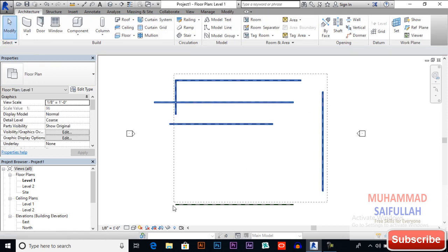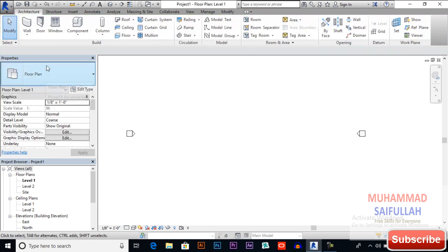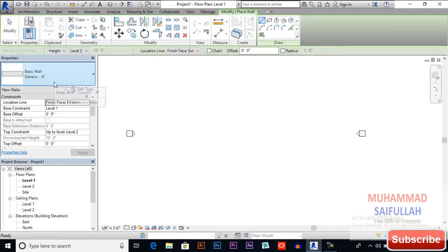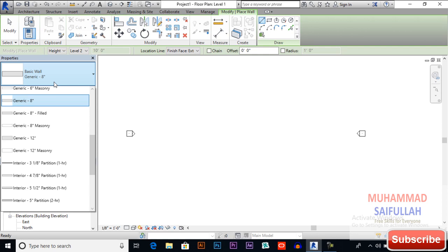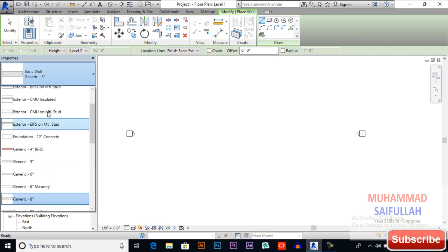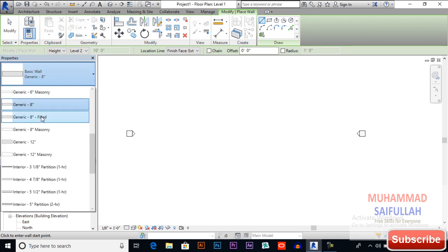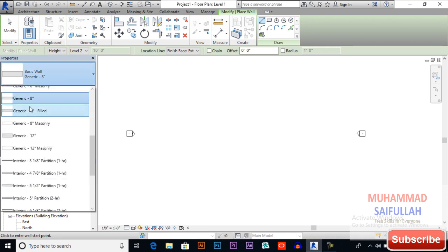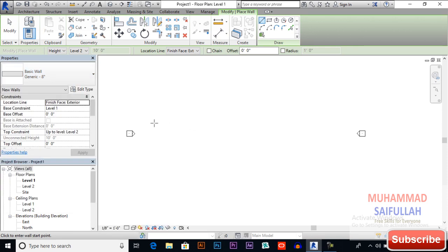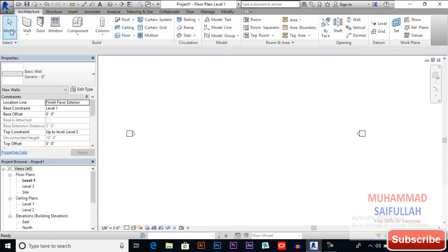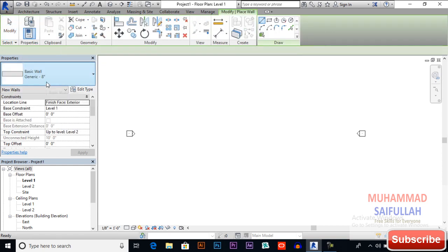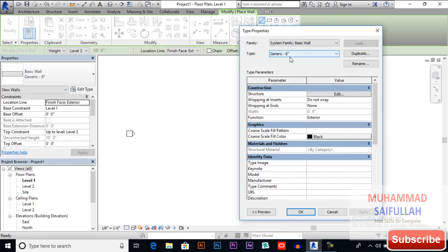Now I will discuss some more things. You can select or change wall types. We already discussed it. Now I want to make changes in some of my wall types. For example, there is no 9 inches wall here, so I want one of my walls to be 9 inches thick. So what I will do, first select a wall type. Now edit your type.